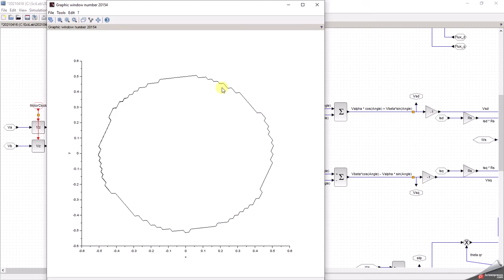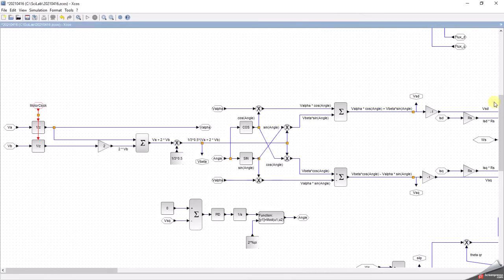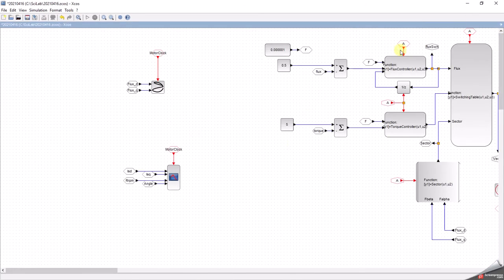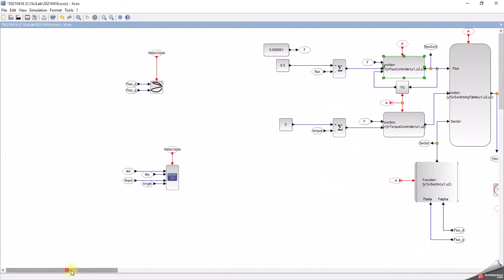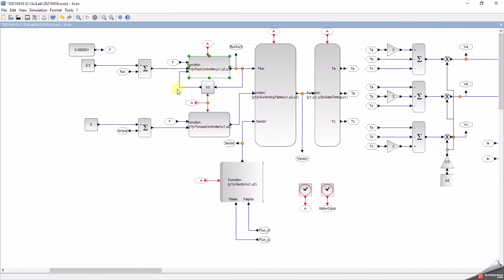And we control that by switching the power device on and off in a certain manner through the use of this bang bang controller, this hysteresis controller. So this hysteresis controller is our controlling element. So we don't have any PIDs in this controller over here. No PIDs certainly means that it's faster. That's what it means.